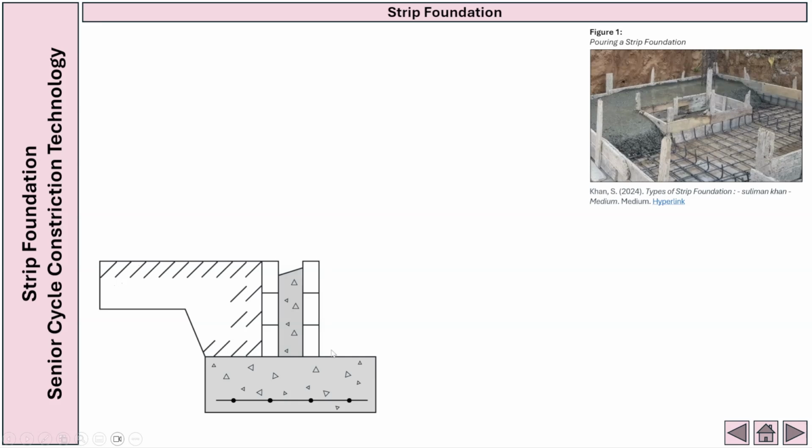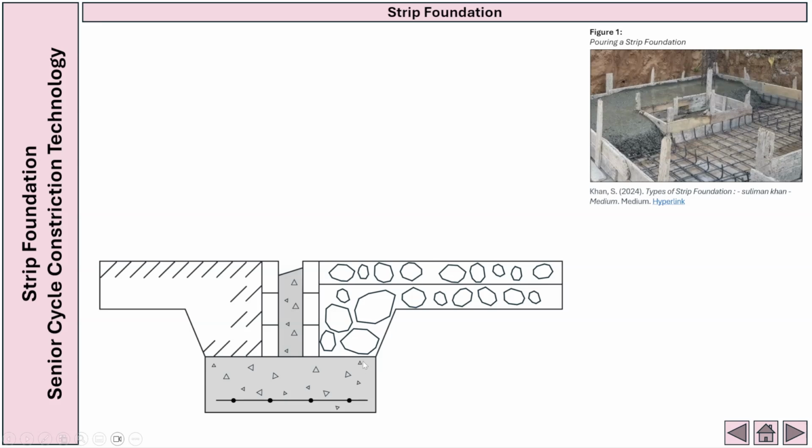Going over to the right side, I did the same thing again, and this is going to be where we put in our hard core. So the same again, went up at 60 degrees, totaling 300 millimeters, went across about 150 millimeters, and then up again 30 millimeters, and then just brought it across again until it met the cavity construction. The distance between this and this is 150, and the distance between here is 150 as well. Now again, just keep in mind we're doing this from a scale of 1:10, so that 150 is actually going to be 15 and 15.